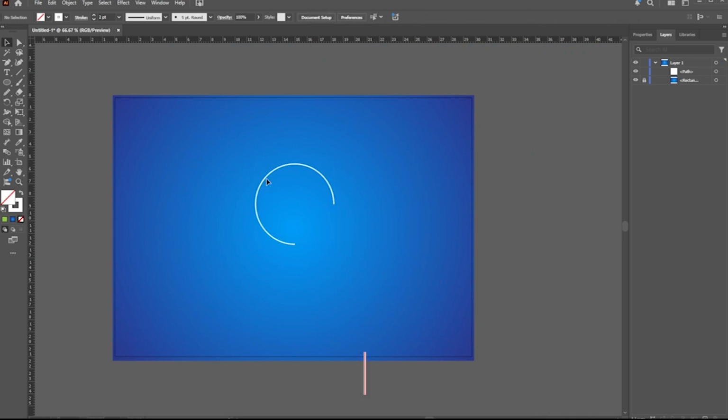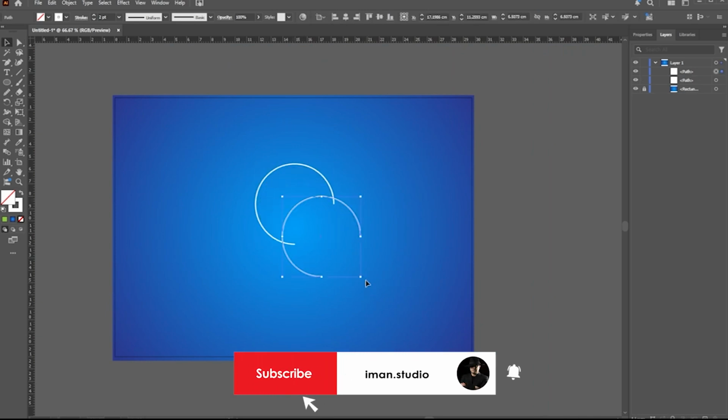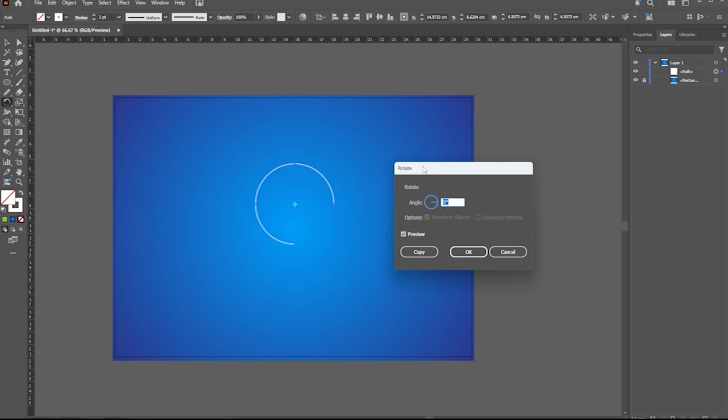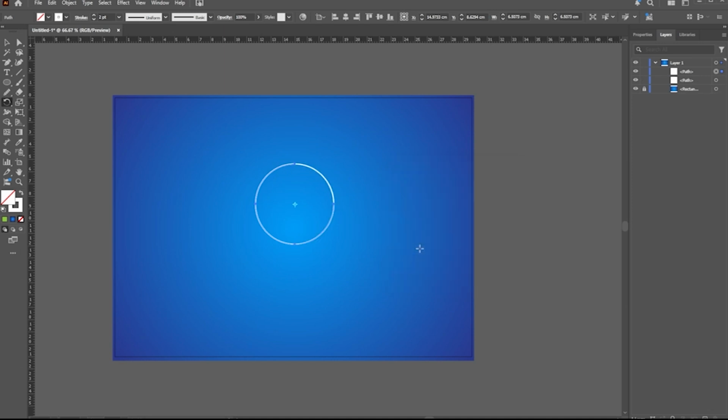Okay, deleting. Okay, I have my form. I am going to use the Alt key to make a copy of it. I am going to rotate it around. In the previous session we discussed reflect, and today I want to show you how to get more professional with copying. You saw I copied it with Alt and rotated it completely. Now I am going to go ahead and select the rotation tool. I am going to instruct it to create a copy for me at a 90-degree angle. Alright, I made a copy at that degree, and then I came here and copied it at 90 degrees.